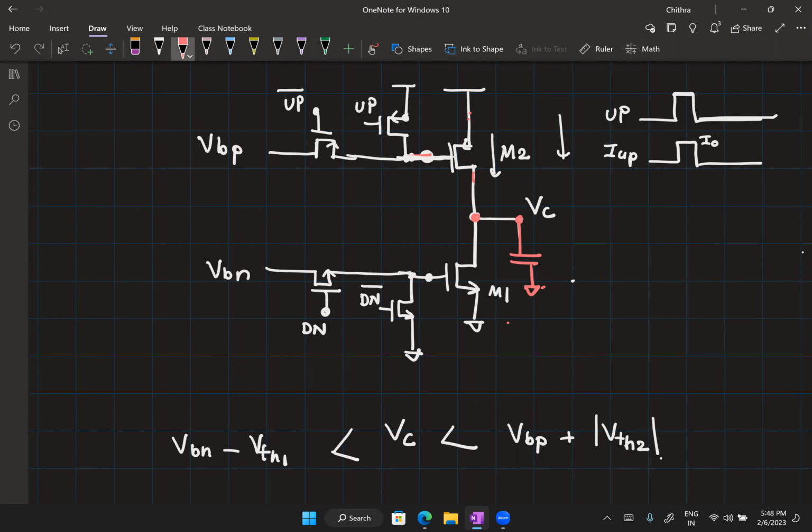So we have a capacitance here, right? Even if you have a switching activity at this node, that can get coupled here. Now, for this to get coupled to the output capacitance, it has to couple through another capacitance, which would be the CGD of this PMOS transistor. So it's already a secondary coupling. Therefore, the effect is going to be much lower.